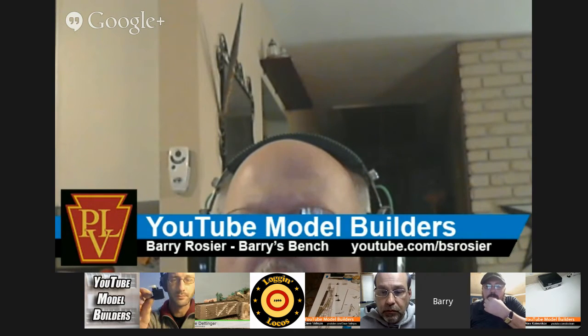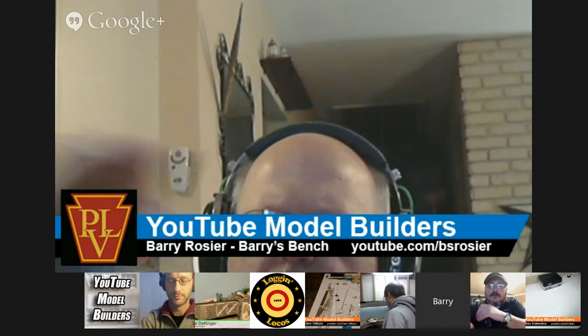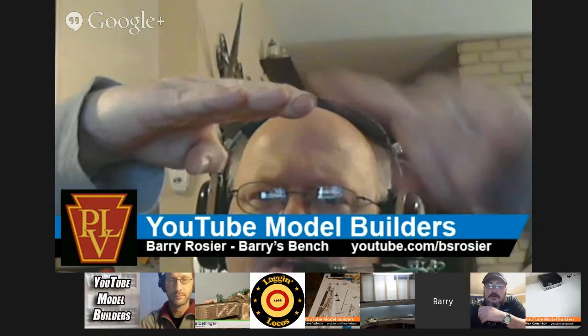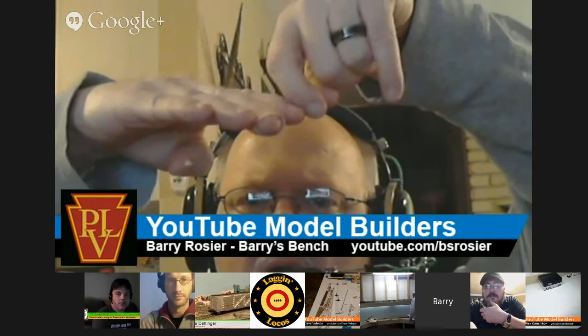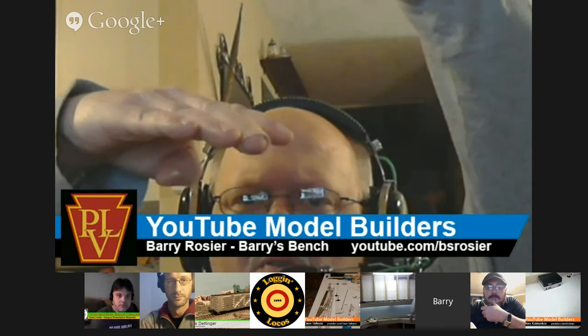My concern with the smaller ones was whether they would have enough point pressure to hold a fixed-point turnout. The 9-gram ones most certainly do. The wood bracket mounts so that the arm goes horizontal, and the base plate has a fulcrum point. You run the wire from your horn through the fulcrum point.